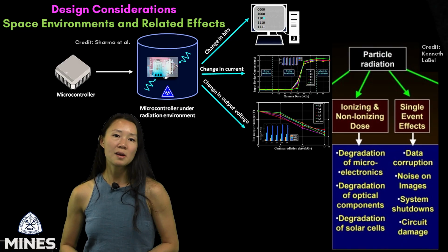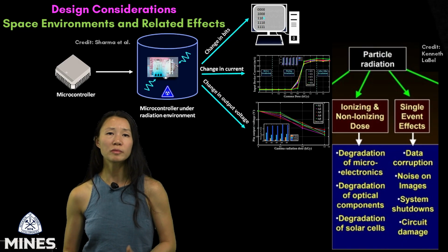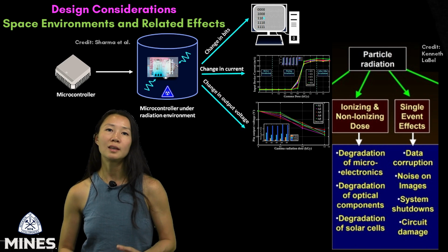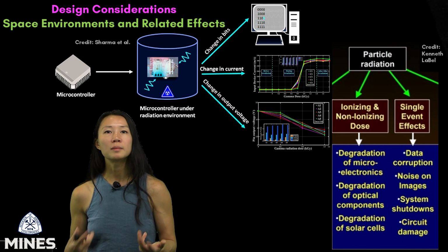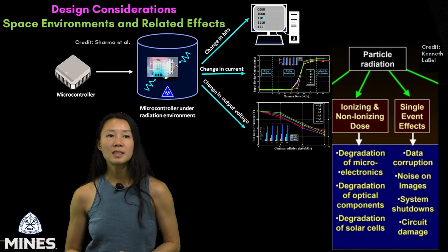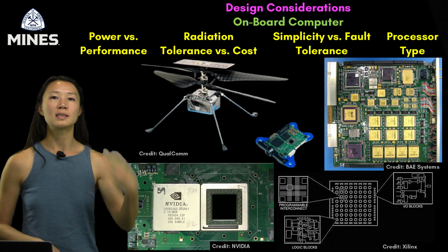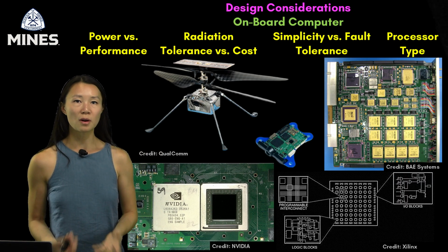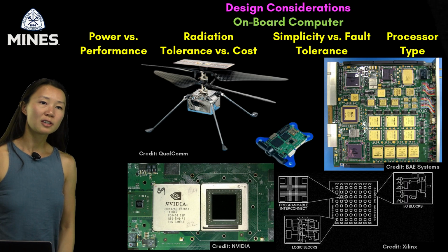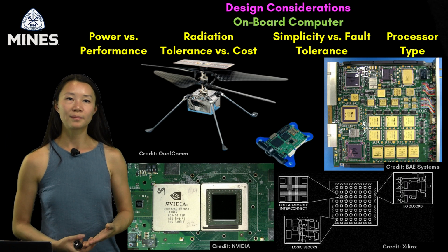We also rely heavily on watchdog timers, which we discussed in the previous slide, which reset the processor if the entire onboard computer becomes unresponsive. And we maintain reset mechanisms and safe mode scripts so the spacecraft can recover without human intervention. One of the most critical decisions you'll make in spacecraft design is the selection of your onboard computer. There are several key trade-offs to consider, and we've highlighted them across the top of this slide.